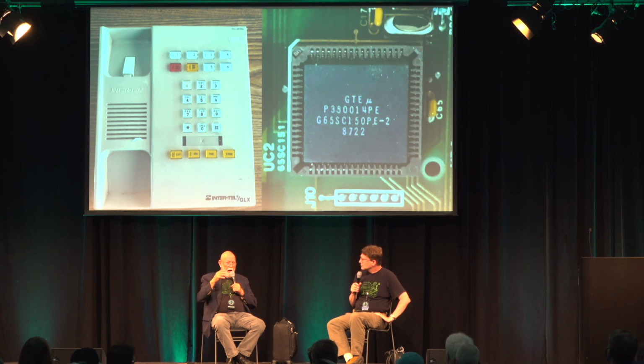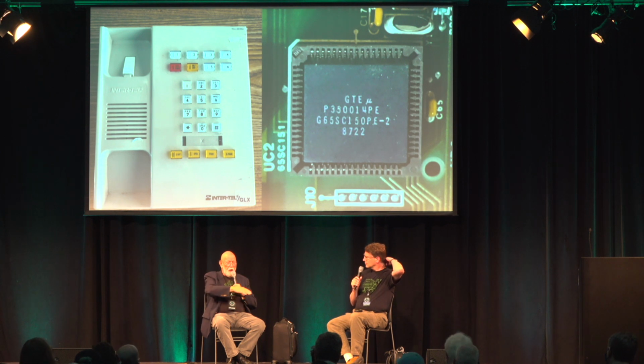But what happened is I knew that what RCA was doing in CMOS was insanity. They had circular transistors and all these other things because they couldn't shut off the channel. Oxide isolation shuts off the channel. But unipolar dope meant you didn't have to go from the P-channel transistor to metal over and then down to the N-channel transistor gate. Unipolar dope poly said you can run poly straight across everything, no problem.